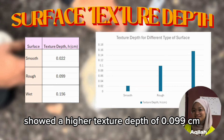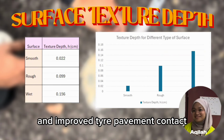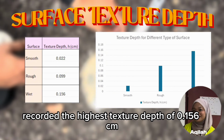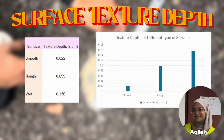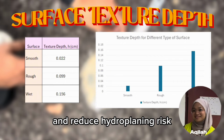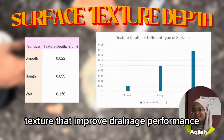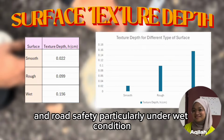The rough surface showed a higher texture depth of 0.099 cm, reflecting better surface roughness and improved tyre-pavement contact. The wet surface recorded the highest texture depth of 0.156 cm, as shown in the bar chart. This indicates deeper surface voids that allow more effective water drainage and reduce hydroplaning risk. Overall, the results show that higher texture depth improves drainage performance and road safety, particularly under wet conditions.